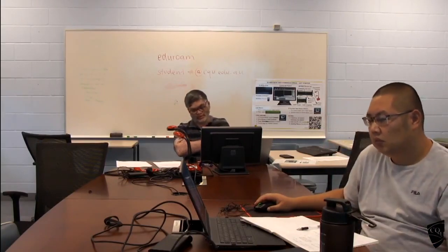So the deflection check needs to be completed for the shorter span in a two-way slab. In a one-way slab, no problem, we have only one span. So we need to assume and check for deflection, and if it is not satisfied, you need to increase and make sure. Okay, so once you have the deflection fixed,